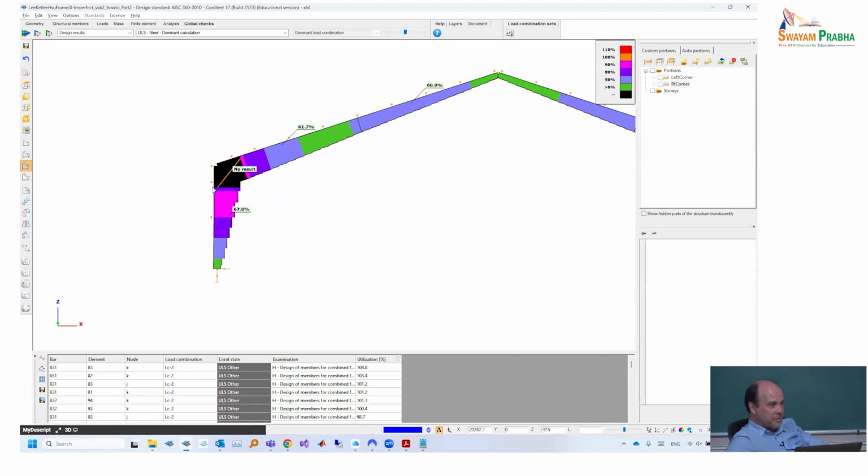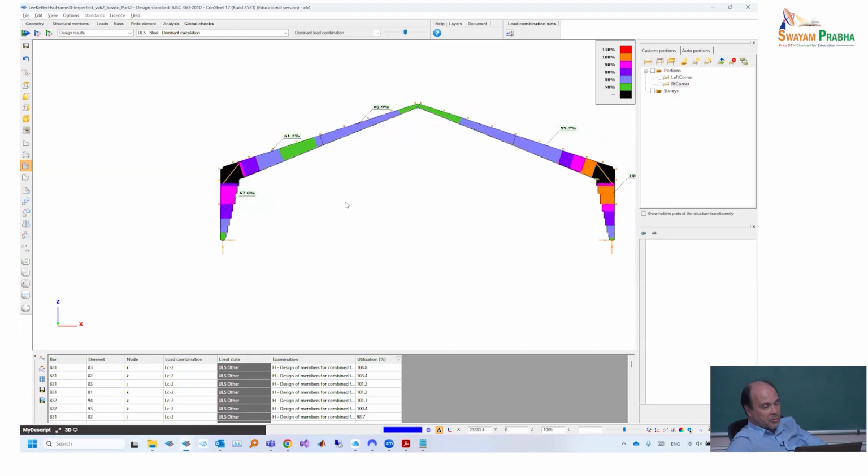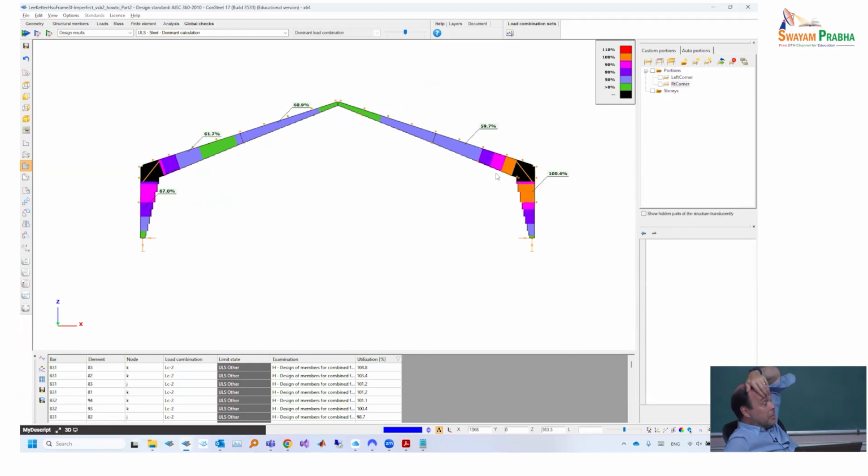So this is the moment where we are adding an additional constraint bar into the stiffness matrix of the system, which will be the leading information regarding warping. We don't let the beam elements do the job because they cannot, and we inject additional information about the compatible deformations. Yeah, it's very interesting, and I'm pretty sure that no one is aware of that. So it's not only more extra welding cost, but it also has a beneficial effect. Yeah, but people still consider a hinge there.